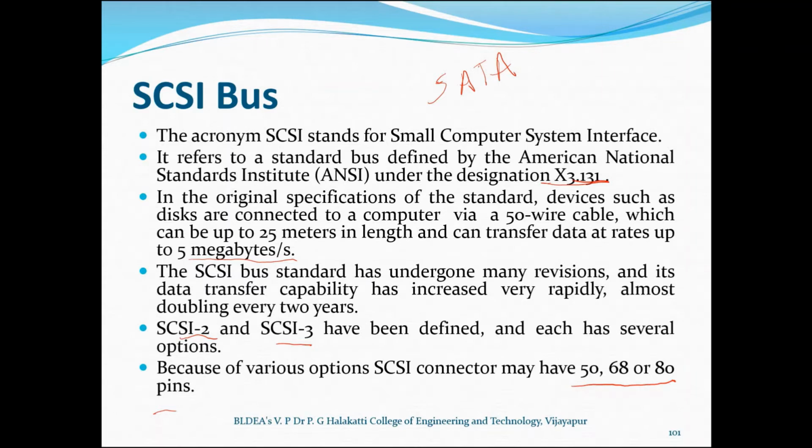So to maximize data transfer, the bus length is limited to 1.6 meters for single-ended transmission and 12 meters for LVDS. The maximum capacity of the bus is 8 devices for a narrow bus and 16 devices for a wide bus.